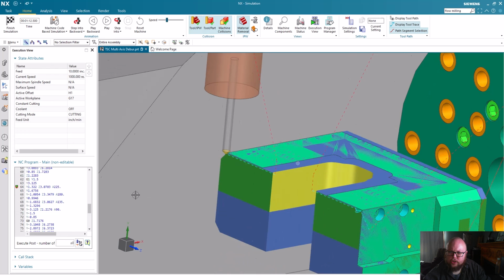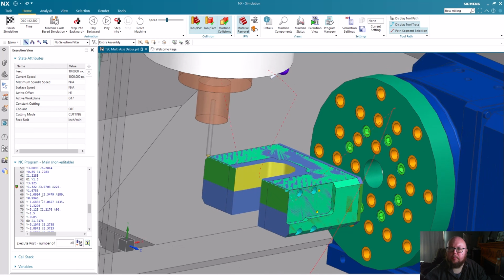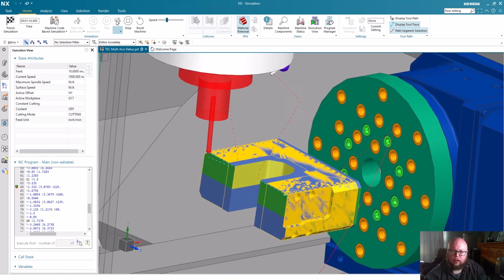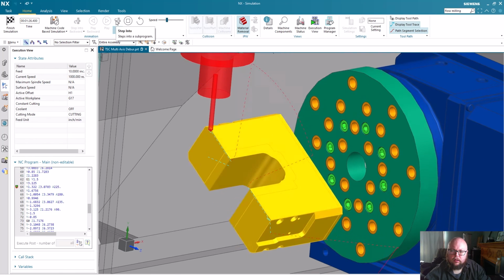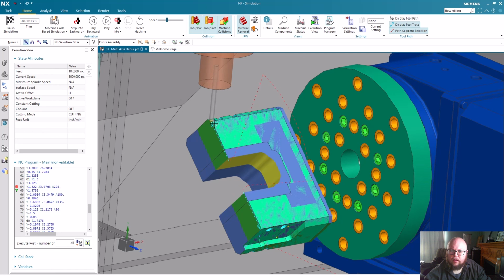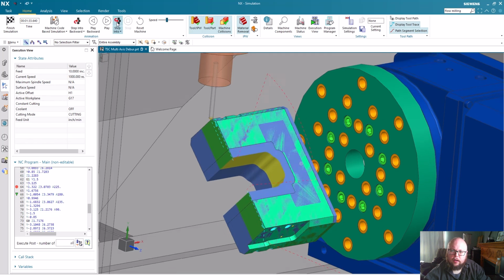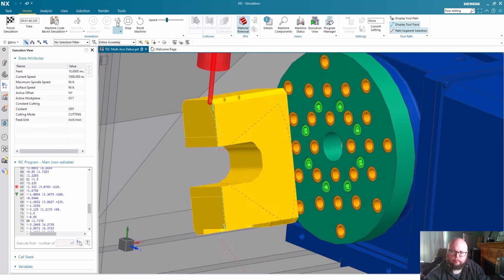But on a 4-axis machine, typically we don't have any type of tool center point control or kind of 5-axis mode to control synchronizing of the linear axes and the rotary axes. So we can see when we try to make this motion, all the axes are trying to just get there as soon as possible. So in doing so, we're going to be resulted with this gouge. The motions are not synced and staying relational to each other, and that's what's causing this gouge motion.